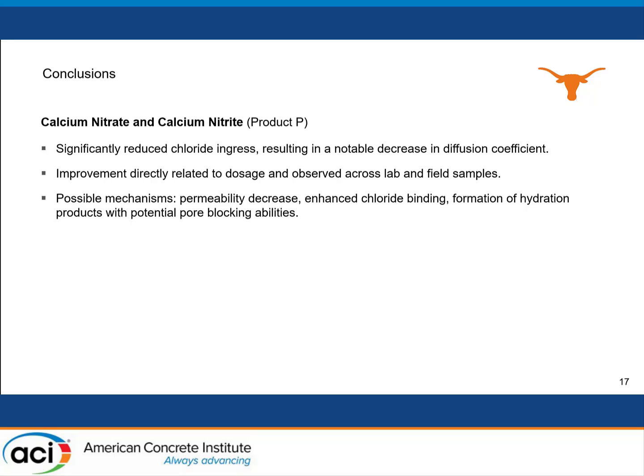We have some ideas about possible mechanisms of why this is happening. Potentially there's a permeability decrease due to enhanced chloride binding or formation of hydration products with some pore-blocking abilities. But again, resistivity and strength have not picked up on this, so we'll have to see what other testing can be done to get at this issue.